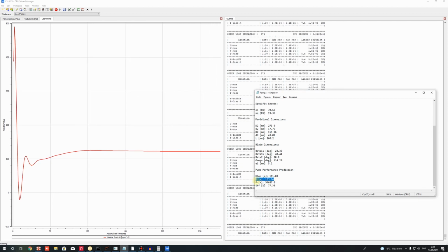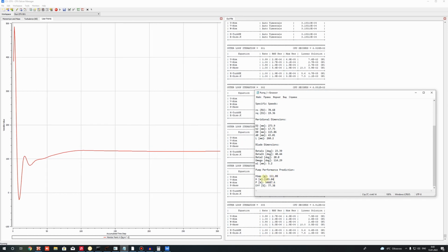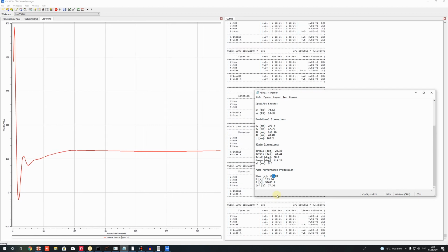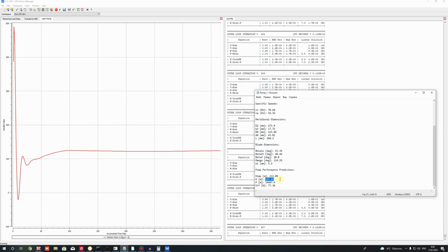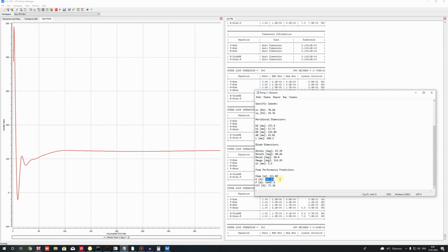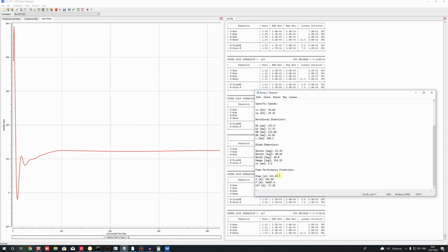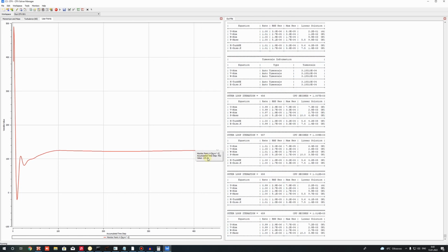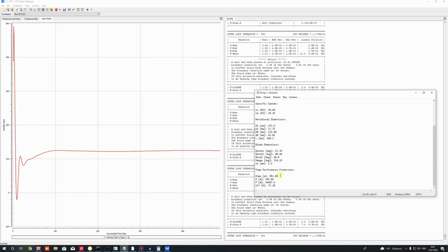The empirical expression defines 7 meters here, something like hydraulic losses in stationary elements like stator vanes or volute or other types of outlet elements. And here we have this value predicted by empirical calculation, and here we have the simulation. Its head is really not much difference with this value.